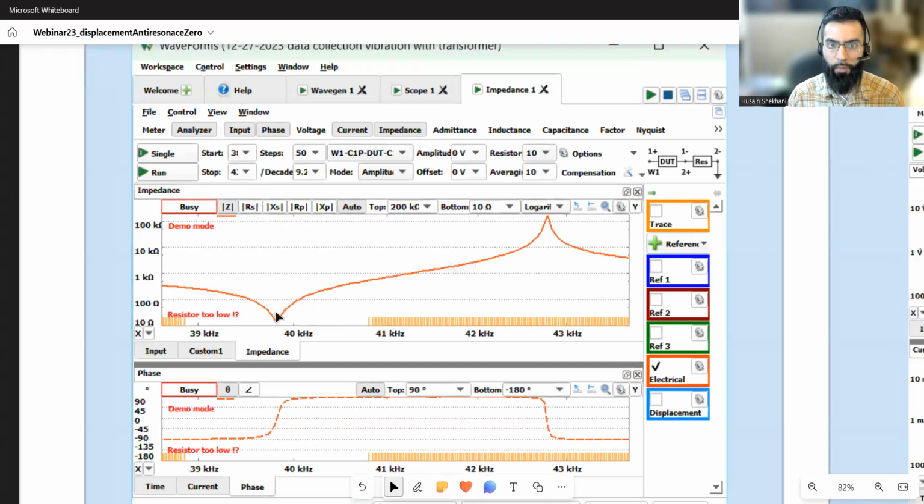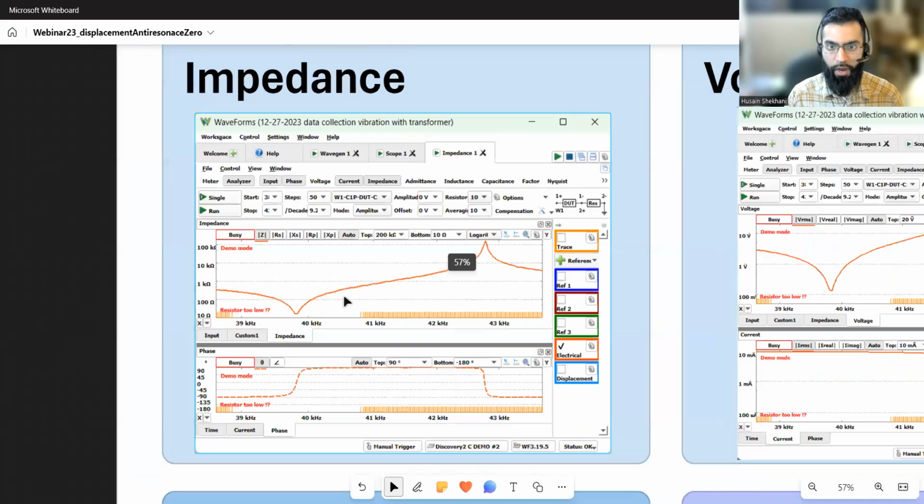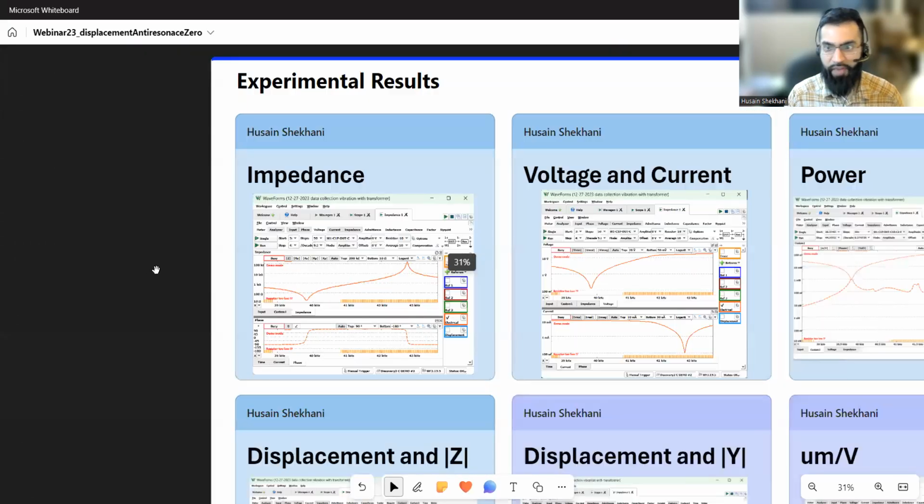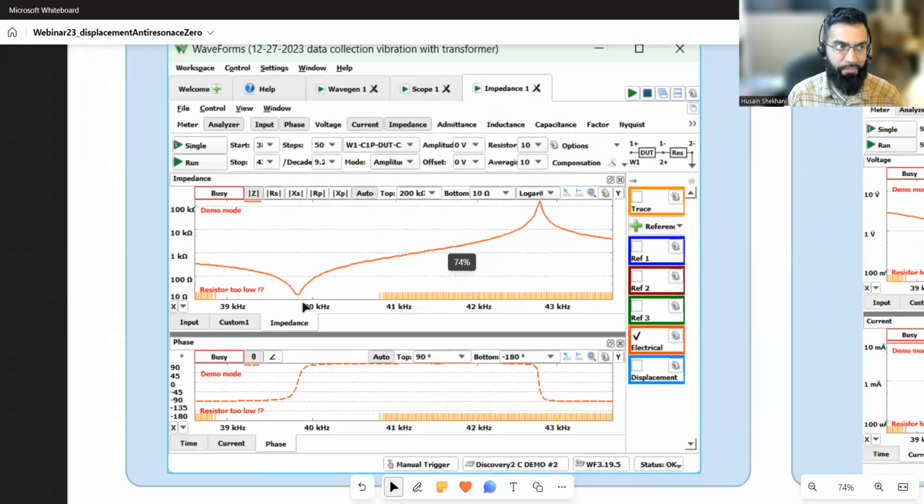You're going to get a lot more power draw at resonance from a constant voltage drive than at anti-resonance. I think many of us understand that. So in order to even out the power, so that I don't have really low displacement that I can't measure, I have an impedance balancing circuit that will allow me to have more or less constant voltage, constant power draw.